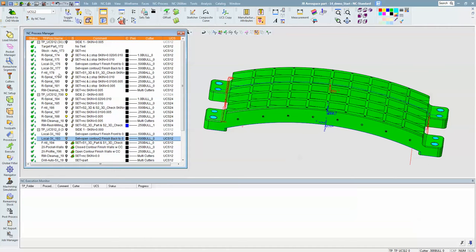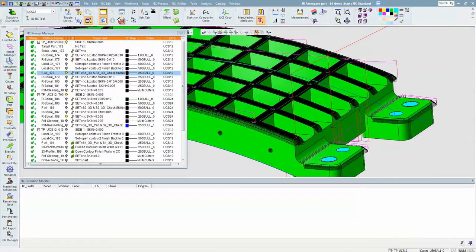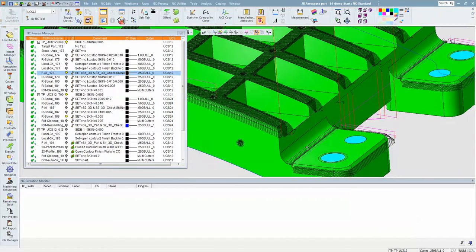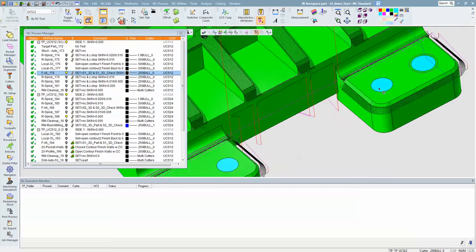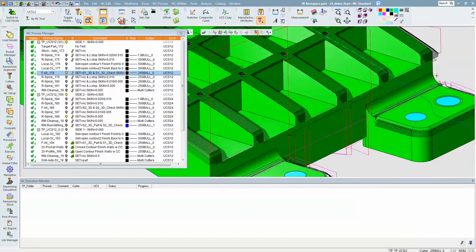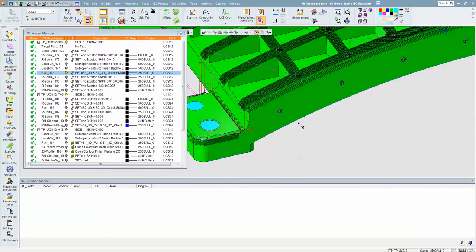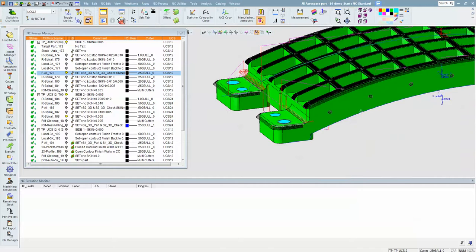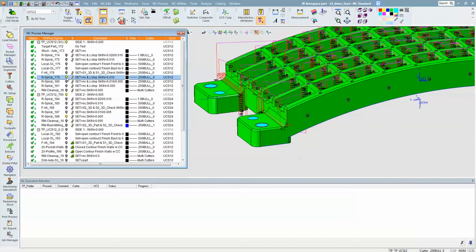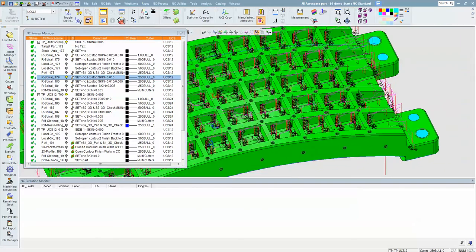And then we got the finish mill all. Now this one is basically cutting everything with a ball cutter that's not flat or horizontal. So it's putting on the chamfers, it's hitting that fillet, it's doing this contour work. So basically all the 3D stuff. And then we got a roughing tool path with a 1/4 inch tool going in and picking out corners.